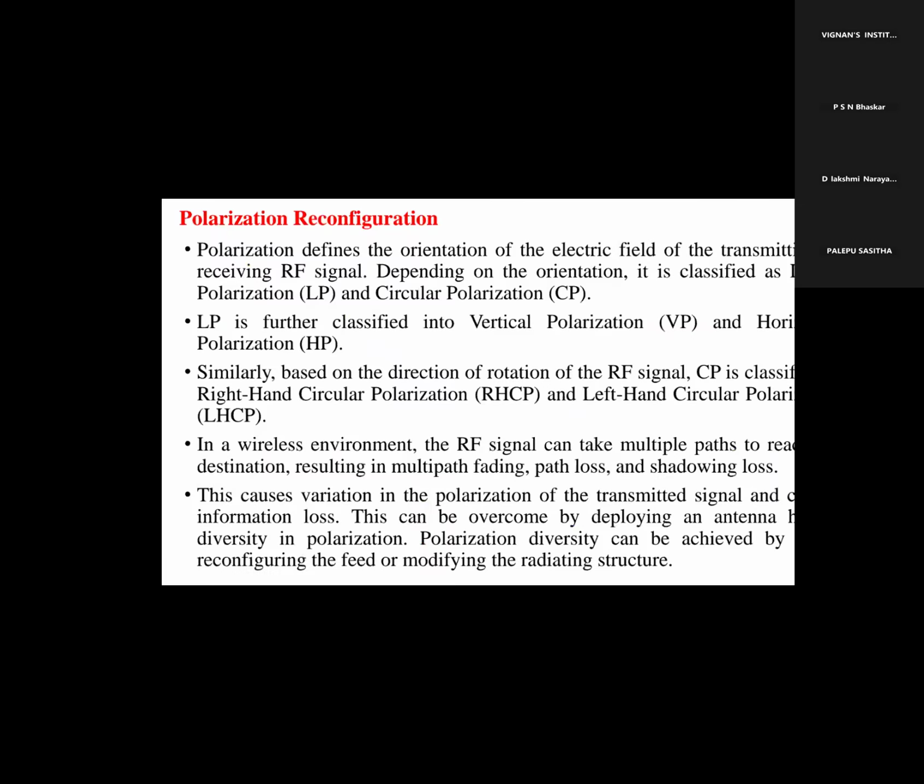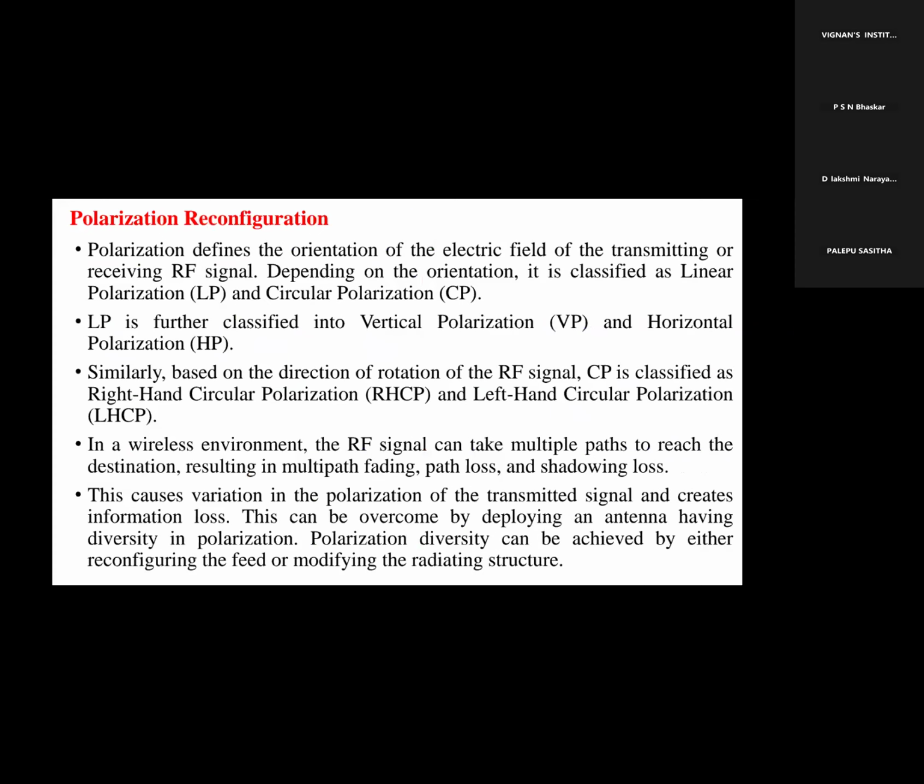Next, we are using polarization reconfiguration. Polarization defines the orientation of the electric field of radiating, transmitting or receiving RF signals. Depending upon the orientation, it is classified as linear polarization and circular polarization. Linear polarization is further classified into horizontal polarization and vertical polarization. Similarly, based on the rotation of the RF signal, circular polarization is classified as right-hand circular polarization as well as left-hand circular polarization.